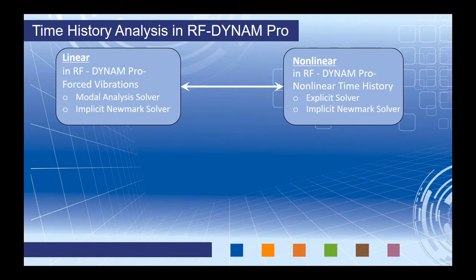Now, again, nonlinearities in the model are replaced, as I've already mentioned, with tension-only members, but also with compression-only members and cables. They're all replaced by truss members. And by the way, a truss member in RFEM is nothing more than a typical beam element that can take both tension and compression. All we've done is release the moments. Now, other nonlinearities may be completely ignored, such as support conditions.